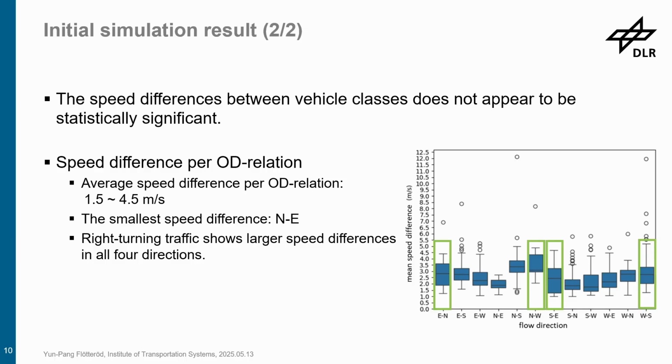We have to put in more pedestrians, or look at the departure time again. It is also possible that we have not considered the roadside parking effect. There are actually roadside parkings in 4 directions. So maybe that's the reason the right turn traffic cannot drive as fast as they can in the simulation. So maybe we need to consider this effect as well.